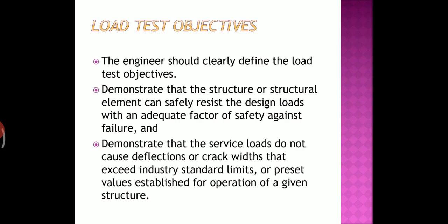Then, the engineer should clearly define the load test objectives: to demonstrate that the structure or structural element can safely resist the design loads with an adequate factor of safety against failure, and to demonstrate that the service loads do not cause deflections or crack widths that exceed industry standard limits or preset values established for operation of a given structure. So these are the things that we have to apply in the load test.